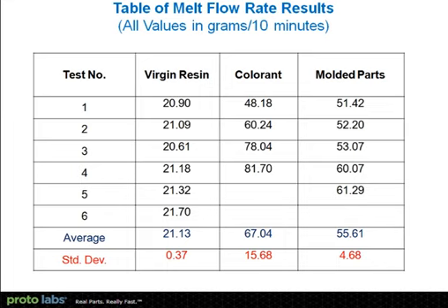When we got a sample of the colorant and ran the colorant pure through the melt flow rate tester, you can see what we saw. Not only is the colorant melt flow rate rather high, but the colorant is unstable. These measurements are made 15 seconds apart on a single sample weighing about 3 grams. And the material is a moving target. It starts out looking okay, and a minute later, the melt flow rate has gone from high 40s to low 80s. That's a very, very bad sign.